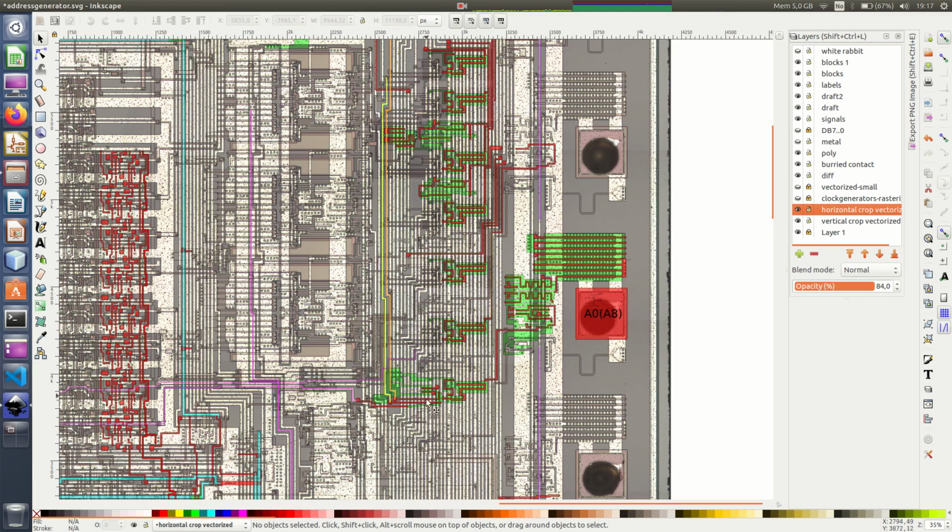And this is a multiplexer, or 1-bit multiplexer. But together with all the other pins, it becomes a multiplexer. So it's a 2-input multiplexer. I'm not sure what the other input is, but that's a multiplexer anyway. So it shares that pad. Oh, the answer is here. You can see this is also A8 and A0. So I think this is the A8 from something. We will find that out. Why do we have A8 there? So we will have to do simulation.